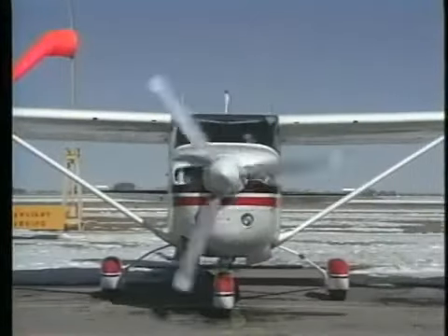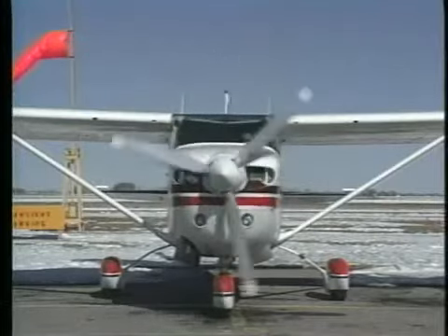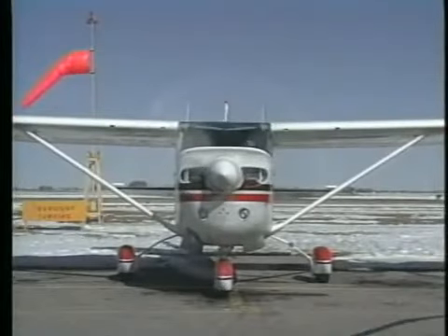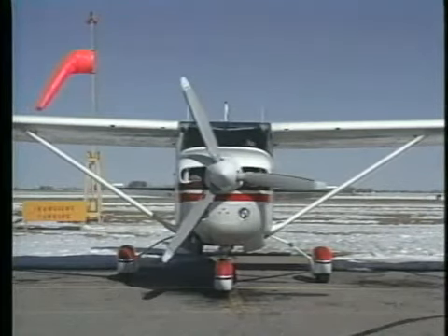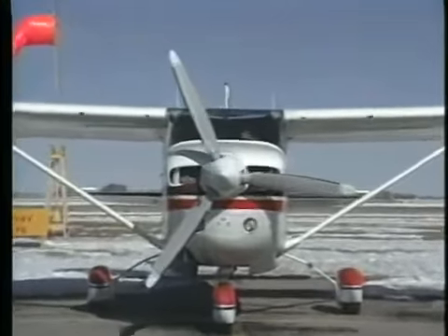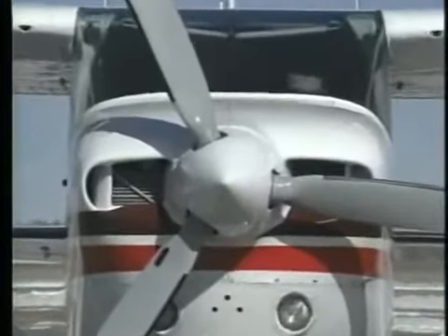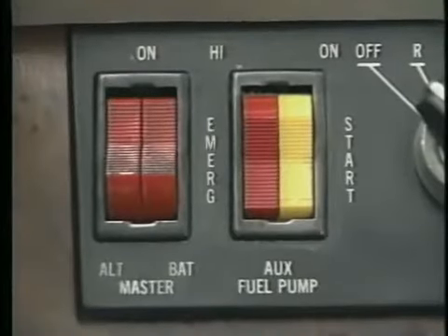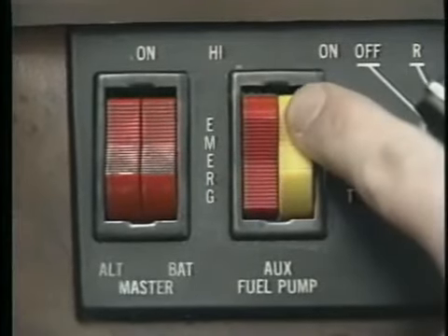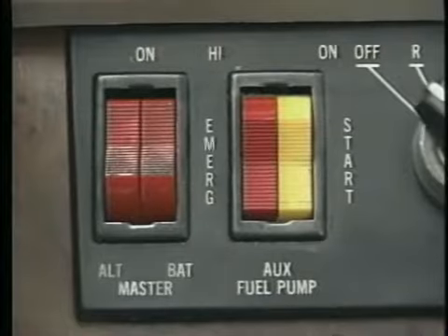Although fuel injection has many benefits, you may experience some problems with the system, particularly when attempting to start a hot engine. The problems occur after shutting down the engine as the air temperature inside the tightly enclosed cowling increases. The temperature inside the induction system can reach a point where the fuel vaporizes, creating a vapor lock, which effectively blocks the fuel flow. Although the specific starting procedure varies, an auxiliary fuel pump is normally used to clear the fuel vapor and reestablish the fuel flow.